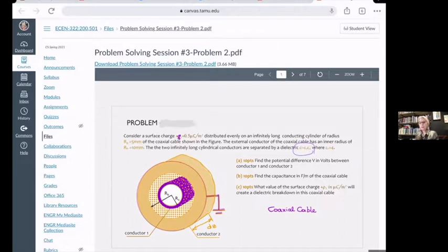This is what we use in a lot of different things, and in TV specifically, because they are high frequencies. If you did not use this cable and you did not have the outside shielding, this cable would perform like an antenna. Instead of being a cable to send power down to your TV set and home from the antenna, it would radiate the whole thing, and so it would not really work practically. You will see a lot of noise on your screen. So this is a very popular cable.